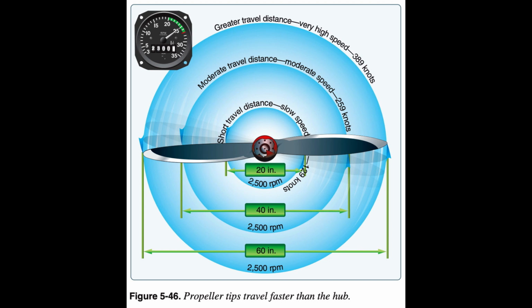Although the mass of air handled per revolution is greater, it is more than offset by a decrease in slipstream velocity and an increase in airspeed. The AOA is still small because the blade angle has been increased with an increase in airspeed.